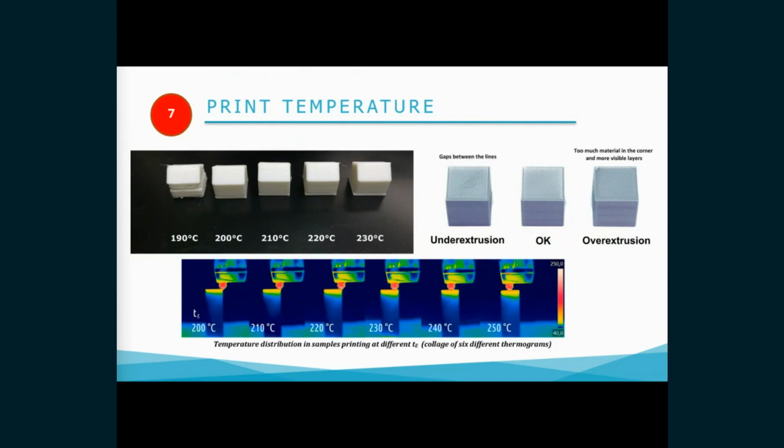Under extrusion occurs when too little filament is extruded during a print. This can result in gaps, missing layers, insufficient smaller layers, and even little dots or holes appearing in the print. Print quality and print strength are compromised when under extrusion occurs. It can be either a material issue or related to print settings or calibration.